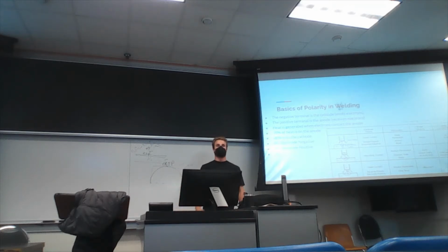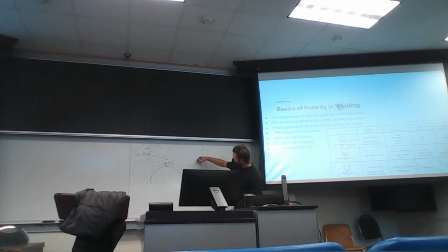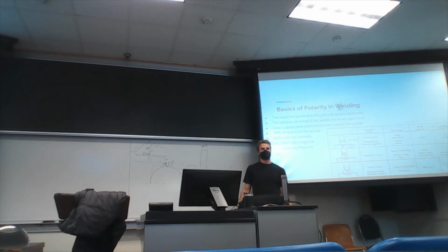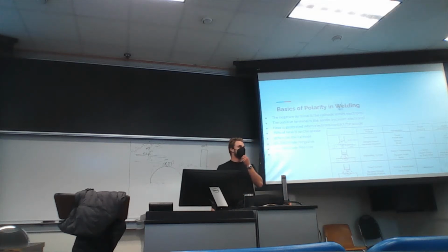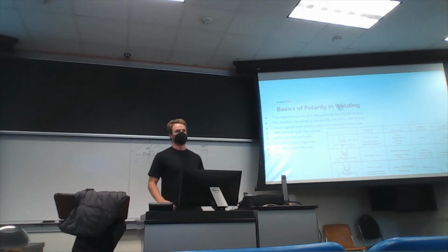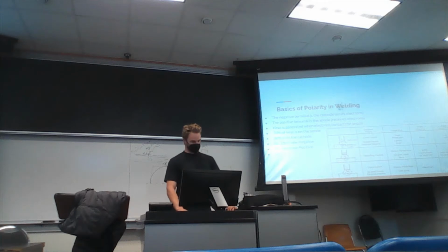To get a more favorable welding cycle, they changed it to the modified square wave, where 25 to 35% of the cycle is DC electropositive cleaning. Yeah? Let's all just review from what I told you in lab.